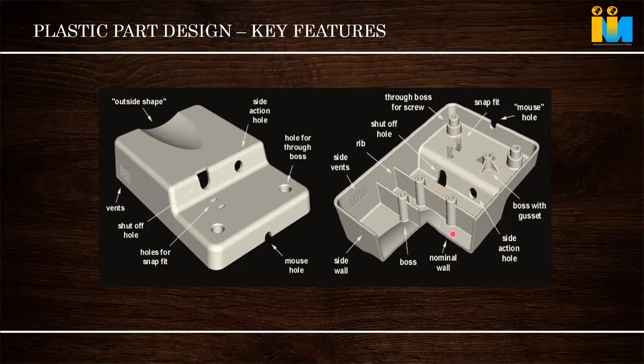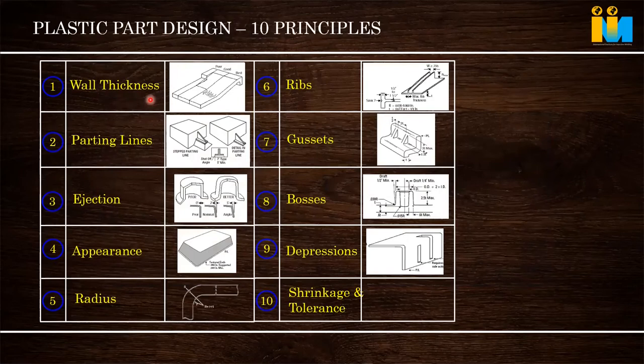So this is known as the nominal wall thickness of the part. When we talk about wall thickness, plastic calls for a uniform wall thickness. Uniform wall thickness means the cooling rate will be similar. If we have to change any wall thickness, the section change has to be smooth, not a sudden step up. This is what is shown here. See, the thickness has so much difference. What happens? A cooling difference will come. One will cool faster and then the part may warp or a sink mark will come. The second is okay, a little bit better.